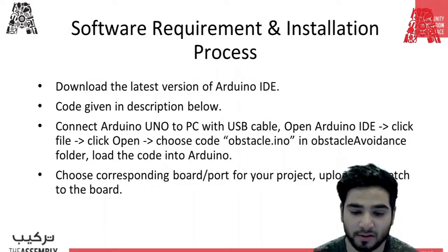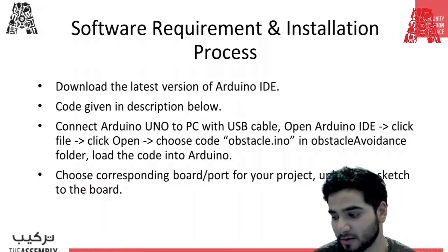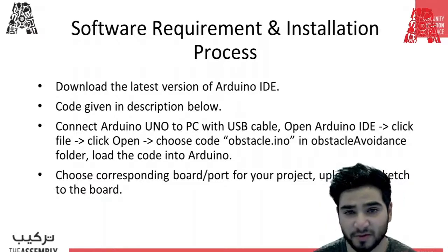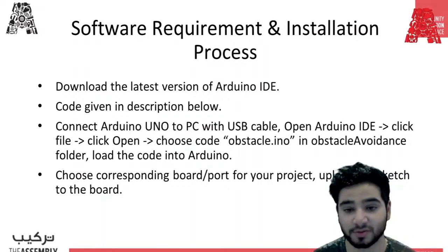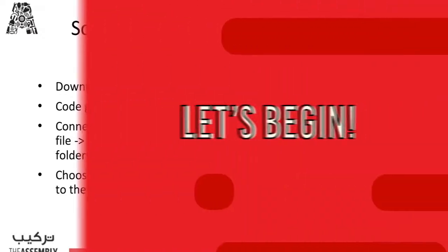Make sure that you choose the port. It's different for each laptop, so just check it. It has to say Arduino. So the port has to be correct, and make sure that you select the Arduino UNO board and then upload the sketch.